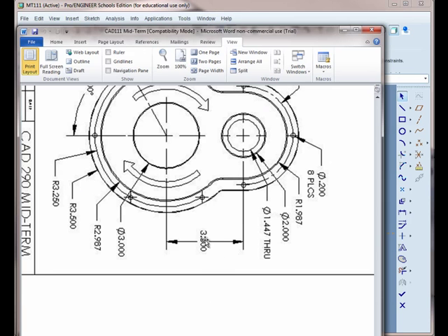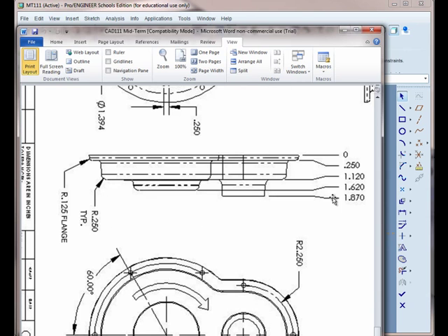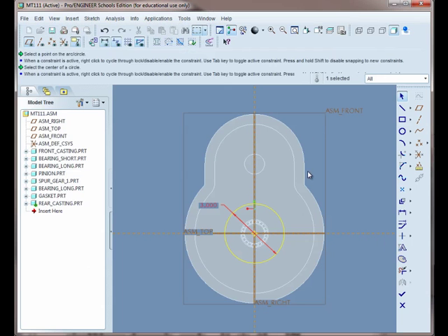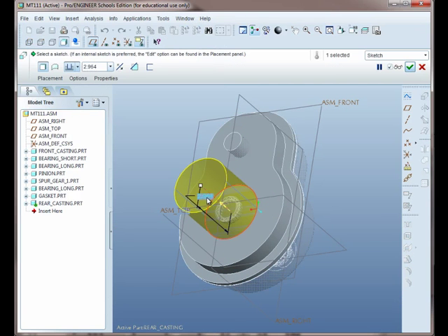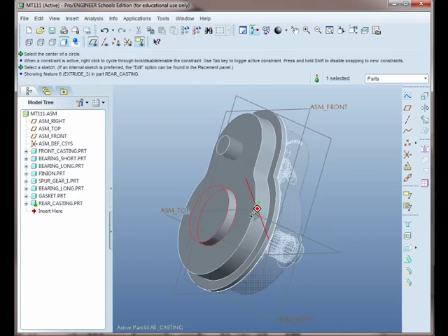And then the depth from here, again we could do the math. If we do the math here, we could see that we have to subtract 1.12 from 1.62, which is basically a 1/2 inch. So 0.5. So this gets extruded a 1/2 inch high. So hit Done, Extrude, 0.5, hit Enter. There it is.